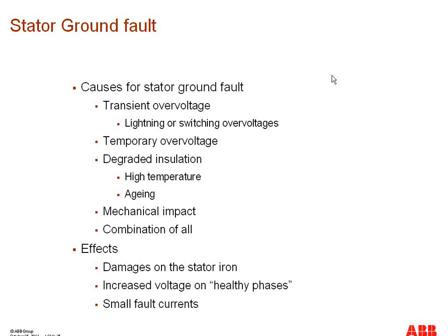So let's talk about the stator ground fault protection now. The causes of stator ground faults can be numerous, and that could be transient overvoltages, temporary overvoltages, aging of the generators causing the degrading of insulation, high temperatures, mechanical impact, or a combination of all. It's quite difficult to pinpoint any single reason for the stator ground faults, but it can be a combination of many reasons.